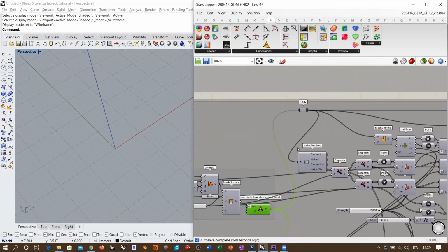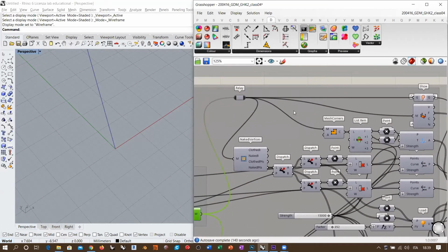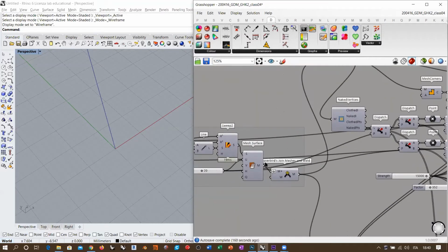Then what I did with this mesh was, well, first of all, the standard things. So I want to show the mesh during the simulation. And this is something peculiar. I will give you a description of the reason why I have this deconstruct mesh here later on, once we run the simulation. And I'm using a couple of anchor points for this system because you see that this is our system. I want this set of panels to pack in these directions. So these 2 points here must be anchored to this position.